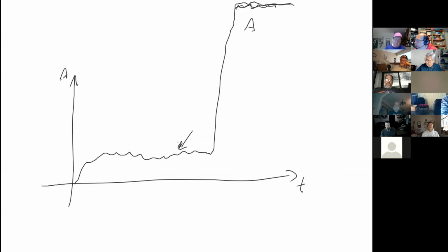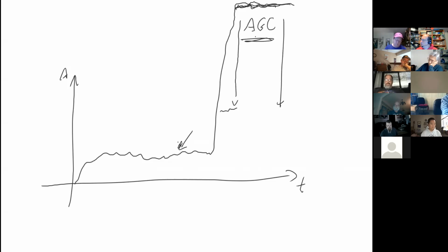So there's something called AGC. Well, gain is how much amplification you have in a circuit. Something called AGC is automatic gain control. And what it does is it says, okay, if I get a really big signal, I'm going to reduce the gain of the receiver so that the volume stays basically constant and it doesn't destroy my ears. And that's known as AGC, or automatic gain control. So it modulates the sound. It basically reduces the sound by reducing the gain of the receiver.